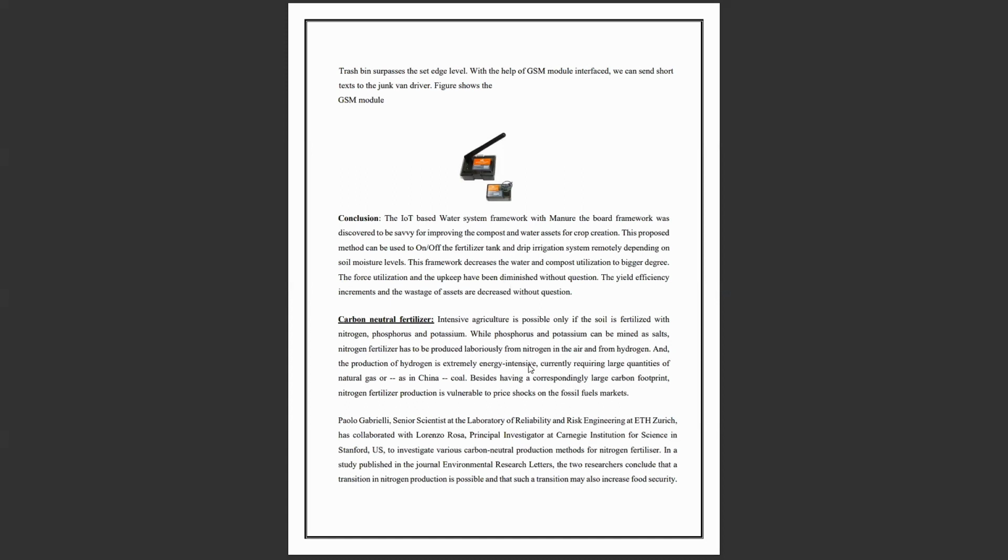Now, let's talk about the existing method. In the sensor-based automated water system framed with IoT, sensor-based irrigation occurs in response to changes in the temperature and humidity in the surroundings. The water flow is regulated by the electric valve. The microcontroller governs the opening and closing of the valve in response to received signals. Plant watering is conducted drop by drop using a sprinkler, and when the moisture level returns to normal as sensed by the sensor, a signal is transmitted to the microcontroller to close the valve. Two mobile devices are connected via GSM, while GSM and the microcontroller are linked through MAX232.